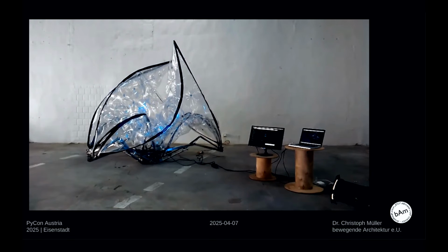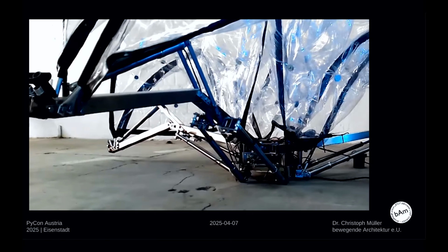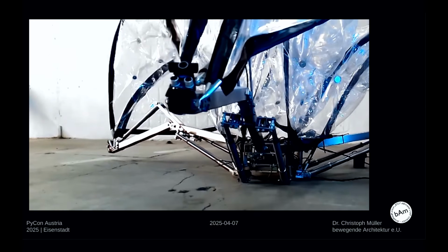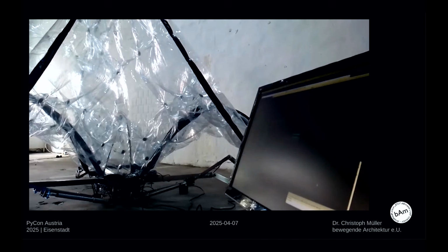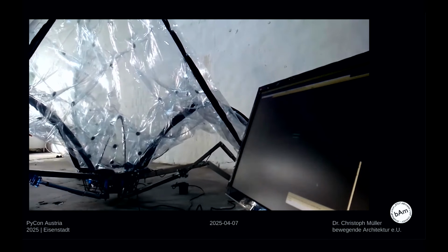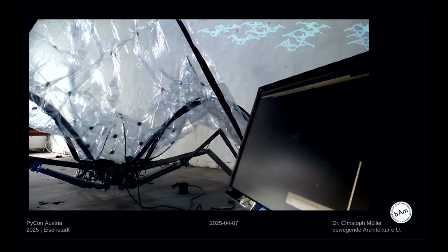This is 3 ultrasonic sensors that are able to produce a rough floor plan of the site. There are cameras, and OpenCV is used for image recognition. And there are microphones in order to control the robots by voice. What you can see here is this simple artificial intelligence that is based on different Python modules that are handling different parts, like the movement, like the recognition, etc. The whole project is based on open hardware, so it's done with Arduino and Raspberry Pi. And the main languages are C and Python.